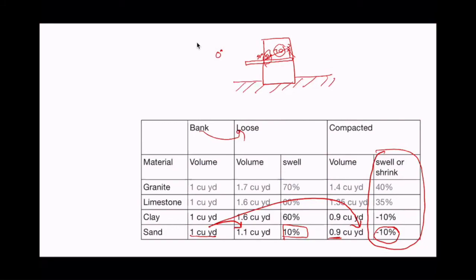Now, they make products that can break up this piece of steel right here. So it's basically a piece of plastic: you have a piece of steel here, a piece of steel here, and then a mounting plate of plastic, and you weld steel to steel and put bolts through here and here, and then you have what's called a thermal break. A thermal break is the opposite of a thermal bridge. It's a way of taking the structure that's continuous between the inside and the outside and disrupting it with something that's not quite as conductive, whether that be plastic or wood.